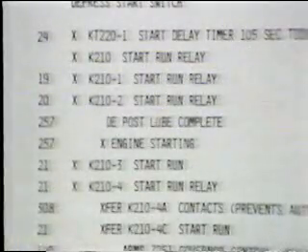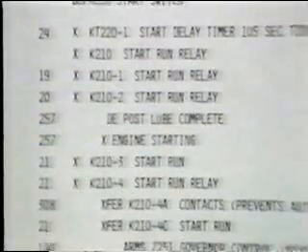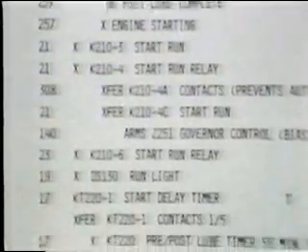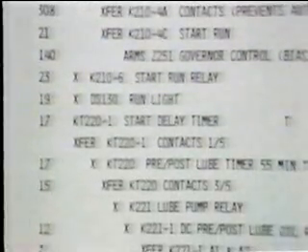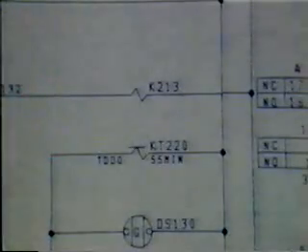At the top of each written logic, there is a legend that describes the symbols used in the logic chart. For example, an X at the beginning of a line indicates that a component has been energized. Similarly, a line with a DE at the beginning indicates that a component has been de-energized. The numbers down the left-hand side of the chart indicate the component's location on the schematic. For example, we see that KT220 is at zone 17. If we check the schematic, we will find KT220's location.